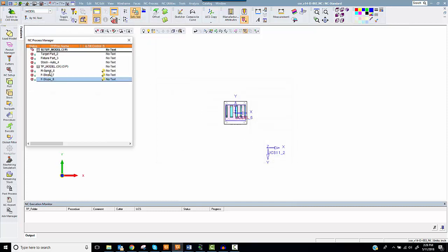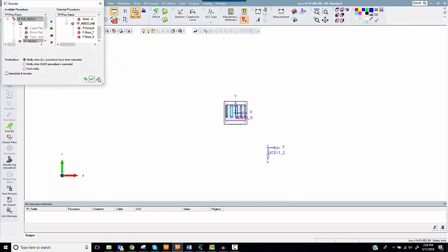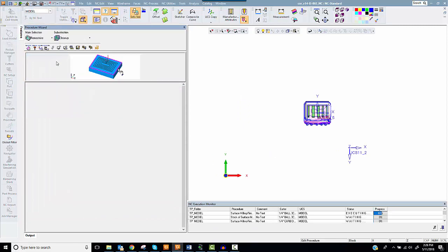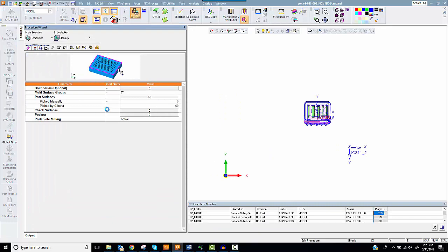Notice this is not part of the 60% I'd mentioned that is completed. It is, however, a situation where 60% of the machining is completed automatically. This helps the programmer focus on the details required to complete the process. I'll copy forward the finish mill by limit angle and change it to a remachine cleanup.